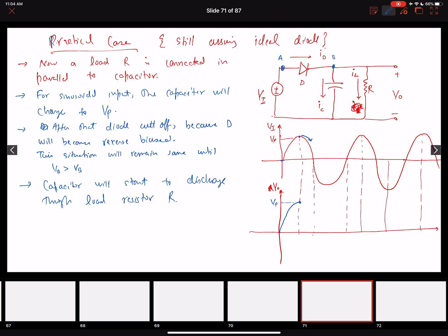That discharge is going to happen until this condition becomes true and the charging starts again and the diode becomes forward biased again. Otherwise, the current continues to flow, and the capacitor discharging will continue to happen. Right, so the capacitor discharge will continue for almost the entire cycle